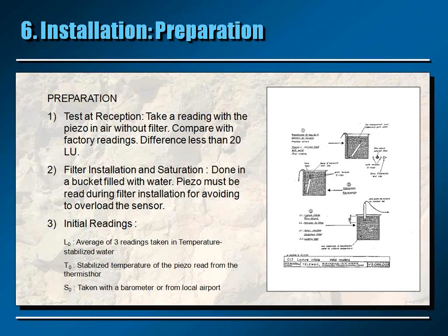First step is to take a reading at reception. When the client receives a piezometer from us, he must read it at zero pressure and make sure that the initial reading is close to the initial zero reading appearing on the calibration sheet.